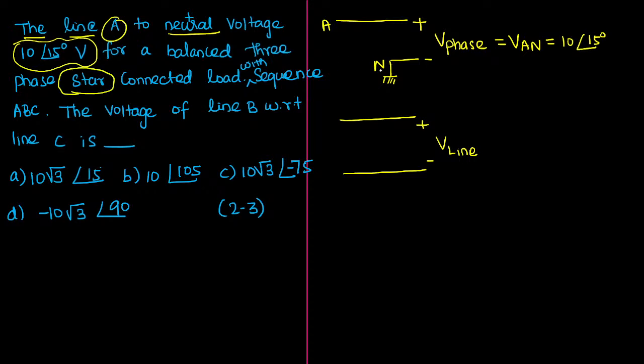See, the moment they told that they are measuring the voltage between line and neutral, a neutral line will exist only in star connection. We saw there are two types of connection. One is delta, another one is star. The external line, the neutral line, one more line, will exist only in the case of star connection. In delta connection, only three lines are possible, whereas in star connection, you can go up to three or four. Three lines means without neutral.